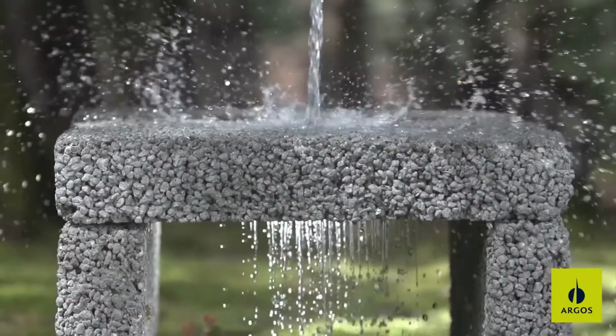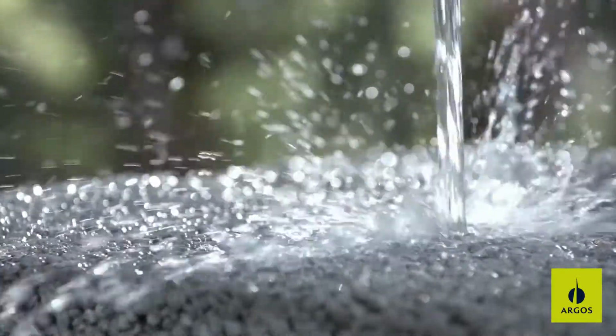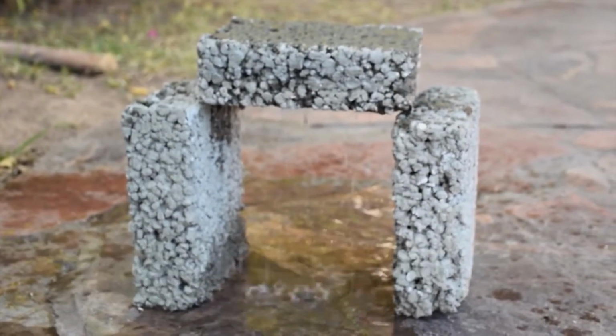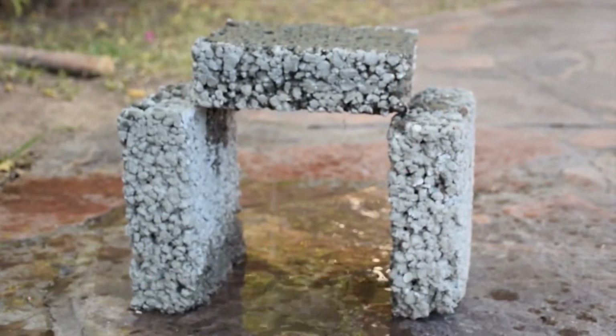The elaborated sample will be placed on hollow support, on which the simple ring infiltrometer test will be carried out in accordance with ASTM C1701 to determine the infiltration rate of the concrete. Logically, the higher the infiltration, the higher the score.